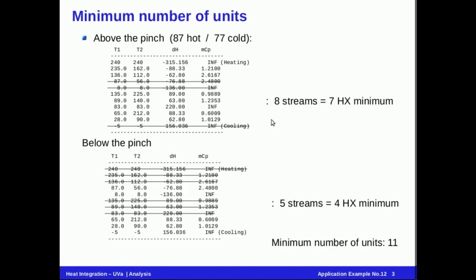This makes 8 streams or parts of streams above the pinch, minus 1, so 7 minimum heat exchangers. And the same thing below the pinch.